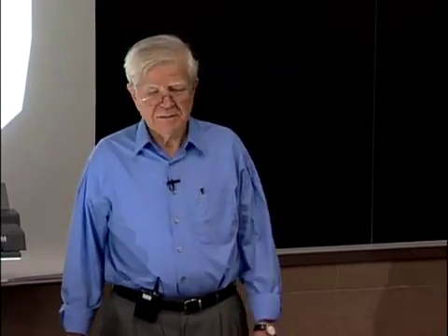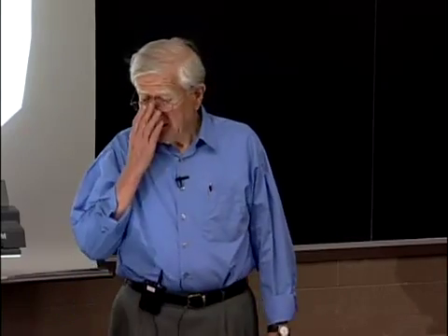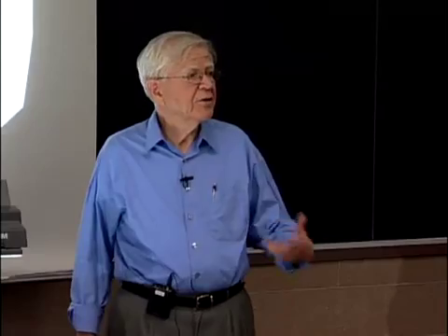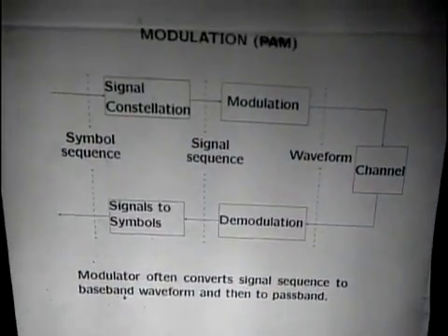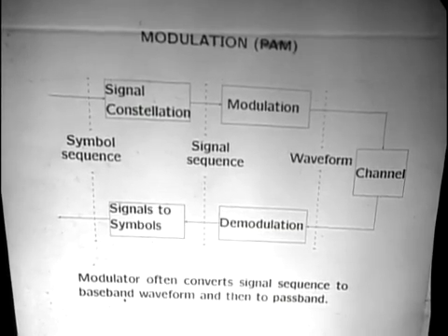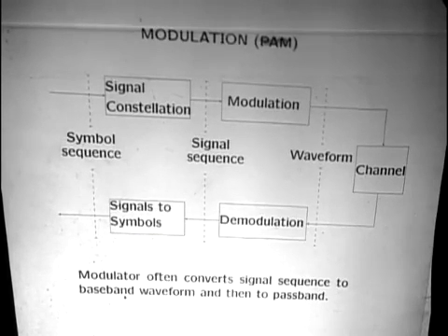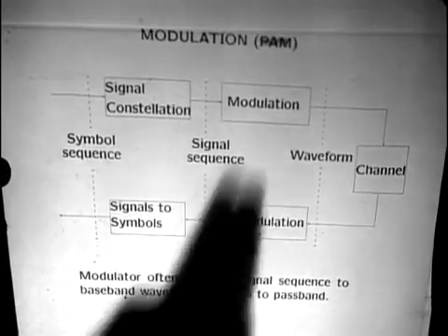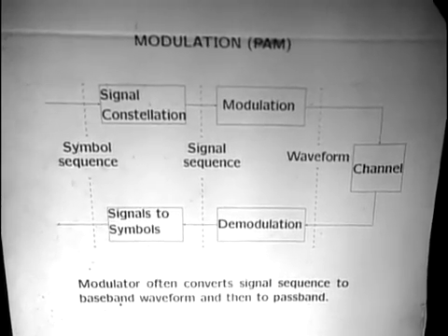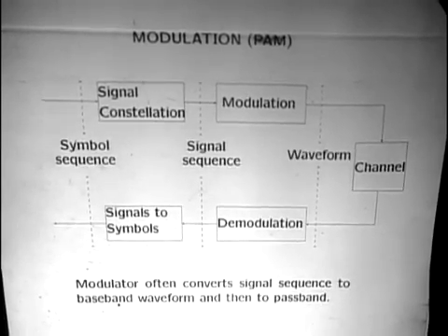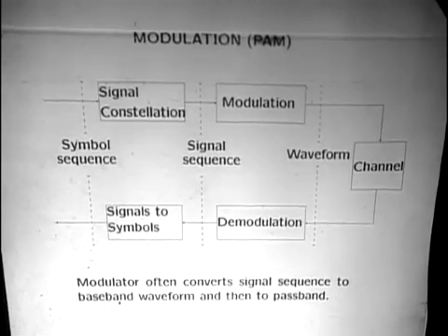Well, there's a little more to it, but not much. And the interesting problem is how do you convert signals into waveforms, which is one of the reasons we went through all of this stuff about L2 waveforms and orthonormal expansions. Okay, so for the time being, we're going to look at modulation and demodulation without worrying about what bandwidth any of this occurs at. So we'll just look at it at baseband.